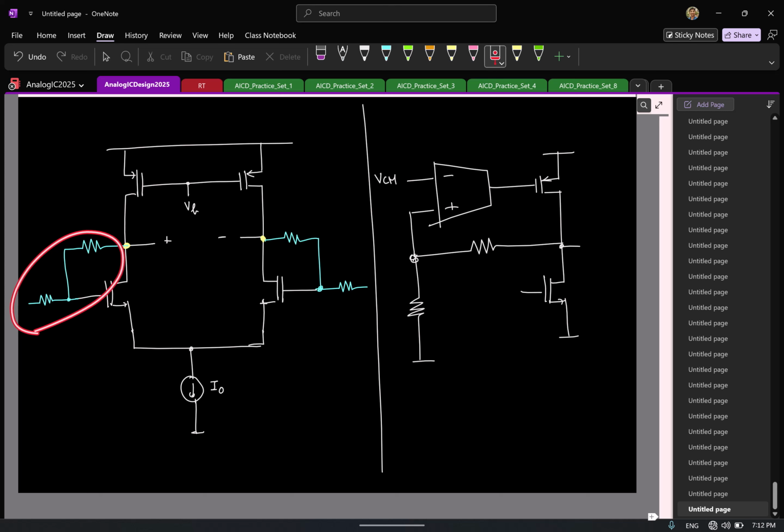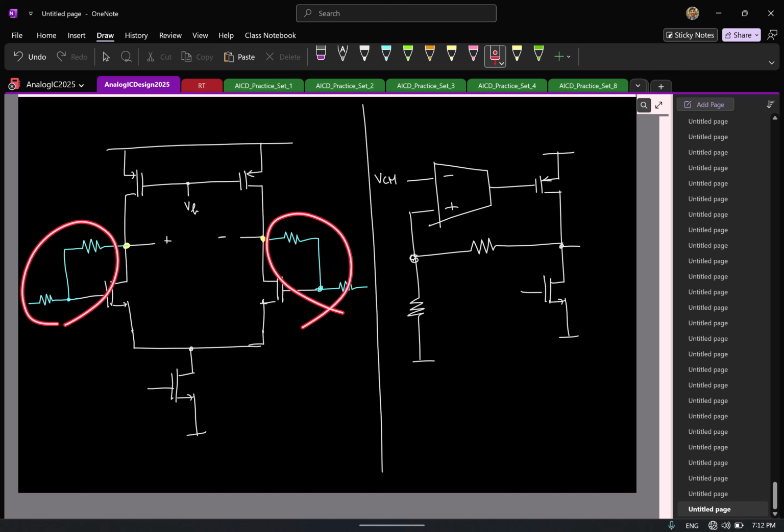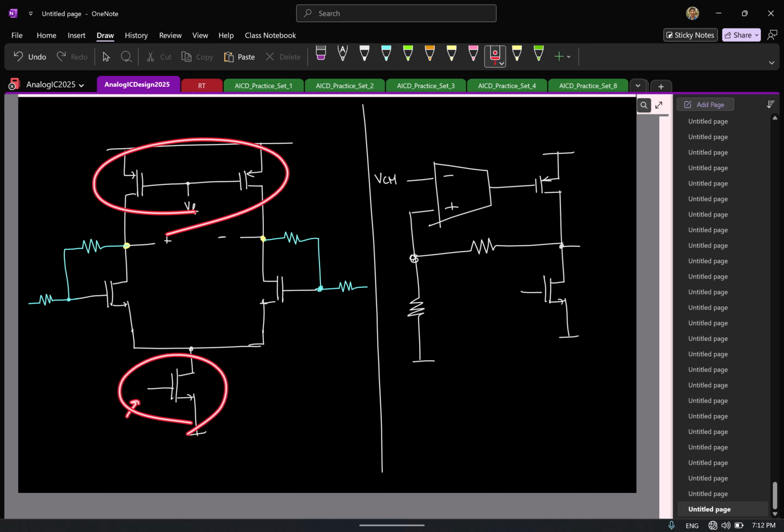So here, although I put the thing in negative feedback, you see that this voltage is still not getting set automatically. You still have independent control on this and the NMOS current source here. So just having the global negative feedback in this particular circuit will not help you. You need to have some other mechanism for setting this voltage, or let us say this voltage. Basically, both current sources cannot be independently biased. You should make sure that one of them is independently biased and set the bias voltage for the other current source based on the first one.